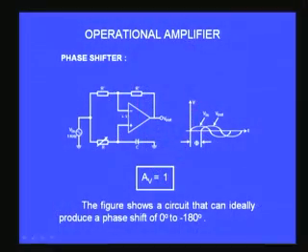So, you can see the circuit which I have shown on the screen. You have the two resistors R prime and R prime, both equal, and in the other branch of the circuit I have an R and a C. R is a variable resistor and C is the capacitor that is connected at the non-inverting input. So, when I have a configuration like this and apply a sine wave input at any finite frequency, you would find the output phase can be varied with reference to the input phase by changing the value of R, with the gain being 1, because R prime and R prime decide the gain, and because they are equal the gain is only 1. So, the gain is 1 for this configuration, but what is the advantage?